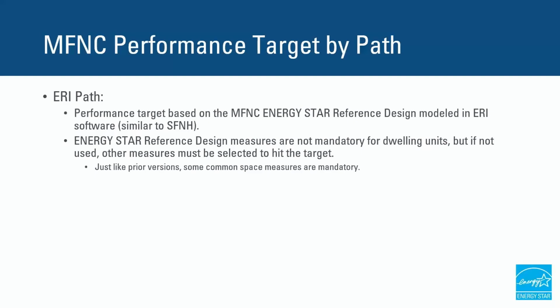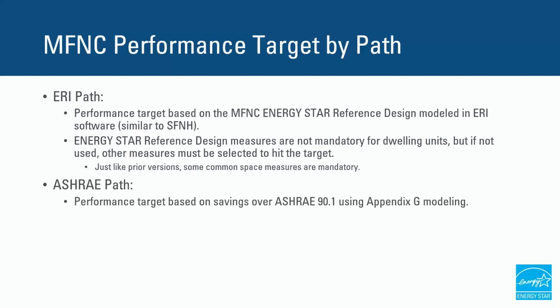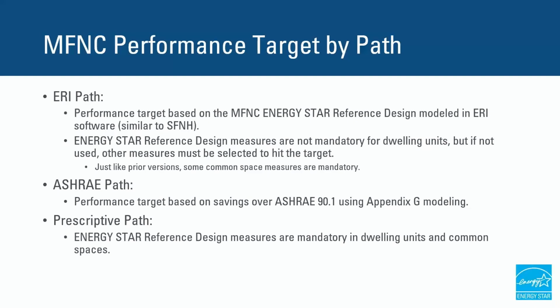Since the ERI model is a dwelling unit model and the program covers the whole building, for the common spaces, some of the reference design measures are required. The next path is the ASHRAE path. This is a whole building modeling path, and the performance target is based on modeling to ASHRAE 90.1 using Appendix G. The final path is the prescriptive path. There's no modeling for this path, but the measures in the reference design are required for the dwelling units and common spaces. So there's no trade-off available.